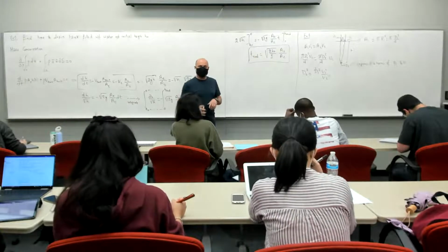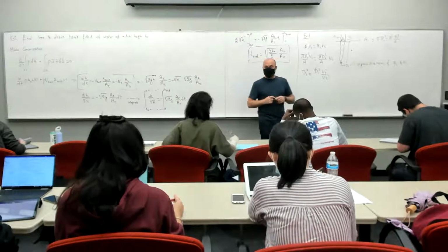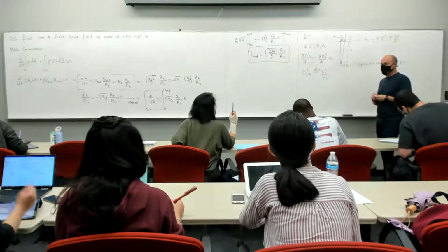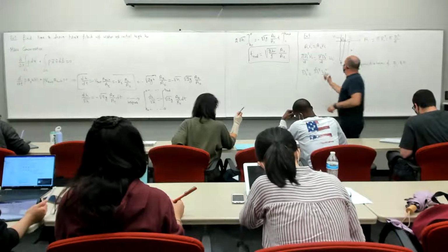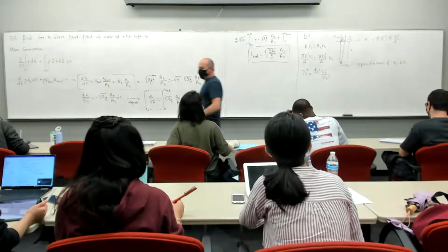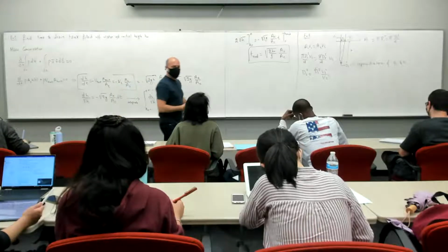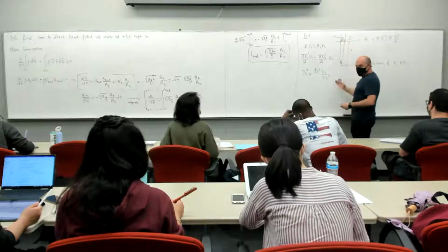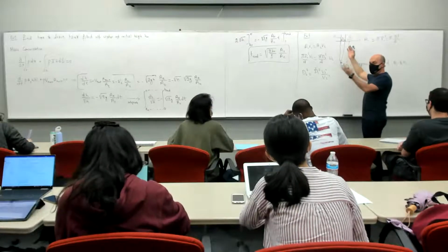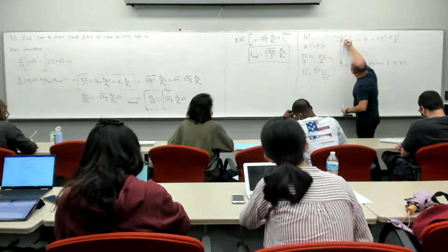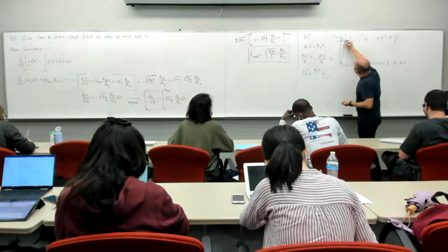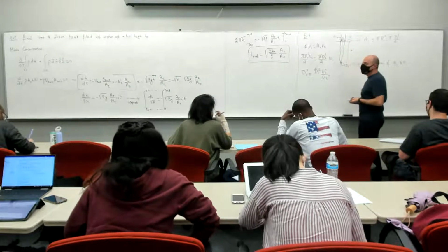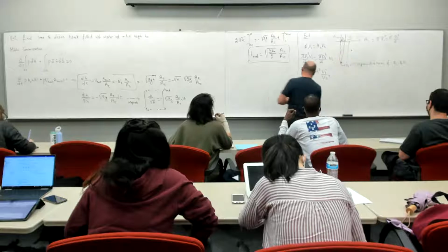Okay. Do you want to continue, Ali? Yeah, I can. Okay. So V1 squared over 2. Okay. So you take a streamline. Let's formalize it. Okay. Let's make it rigorous. Consider a streamline. Assume that the flow is inviscid and that there are nice streamlines. Consider a streamline, say at the center of this jet, from point 1 to point 2. Okay. Now apply Bernoulli. Okay. So what do you get?